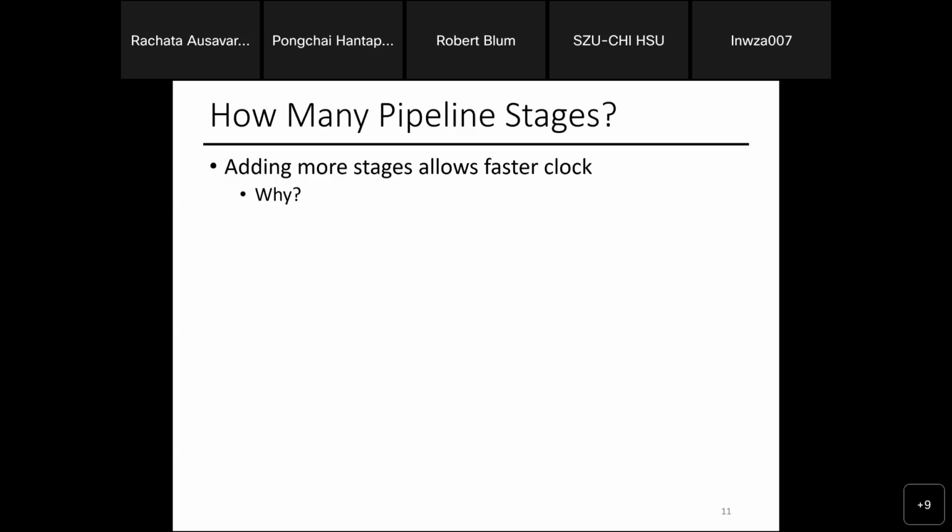For example, remember the assembly question from superscalar, the push kill question from assignment 4, task 2. The one that says, if you see these bit patterns, it becomes push kill with this format, right? Imagine how decode cannot be done in one cycle unless the design is really big, because you need to compare multiple things.